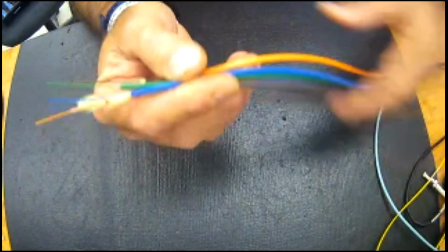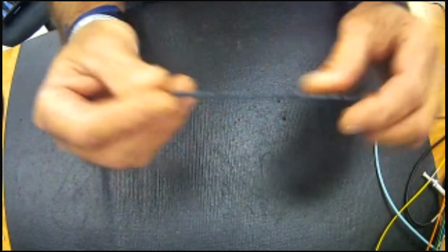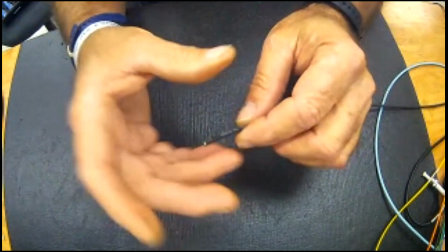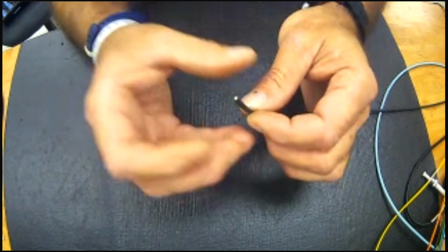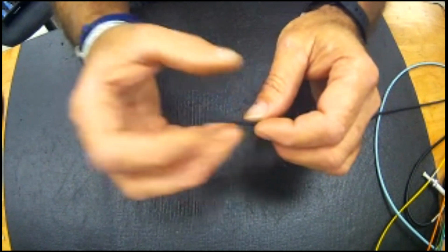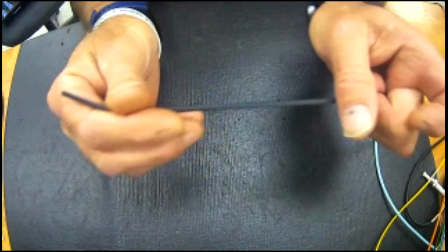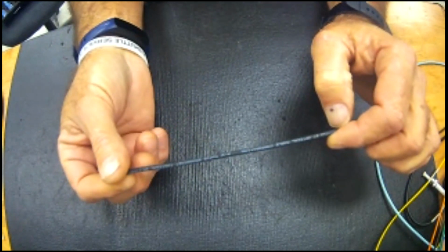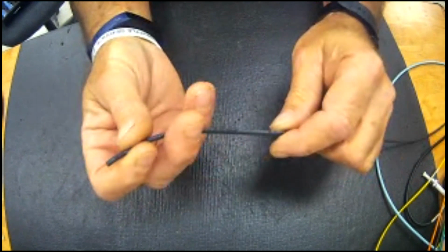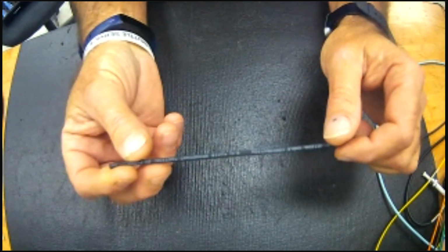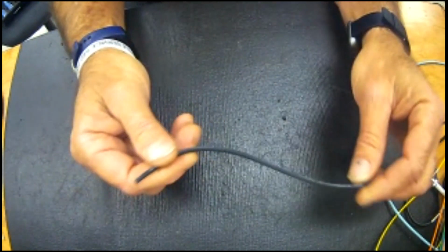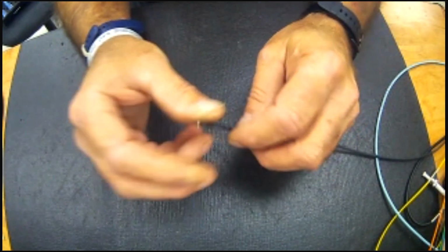I'm actually going to quickly illustrate that and show you what tools are involved. This is actually a 3 millimeter TAC 1. The reason it's tactical is because it is a polyurethane jacket and it has yarn inside of it that's basically bonded to the internal jacket. This has, in a slow pull, almost 1,200 pounds of tensile. I kid you not. You can tie this stuff in a knot and you can pull it pretty hard. It is extremely durable, but I would not consider it a common patch cord for racking.